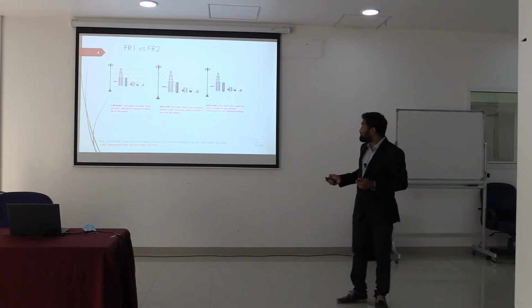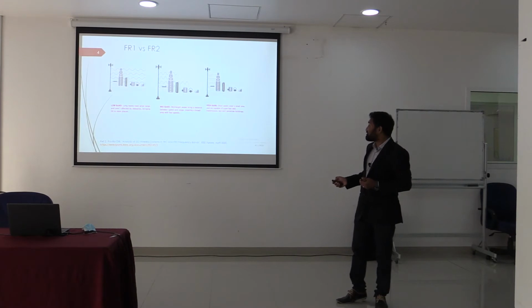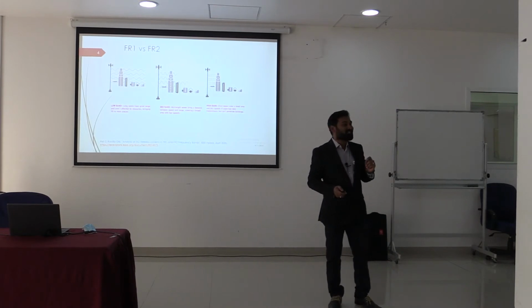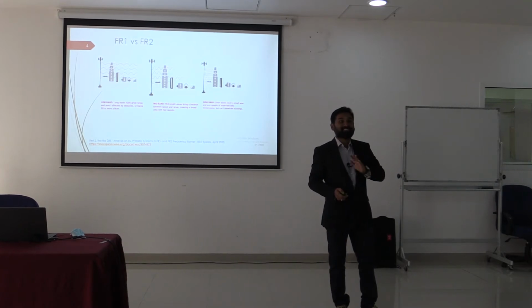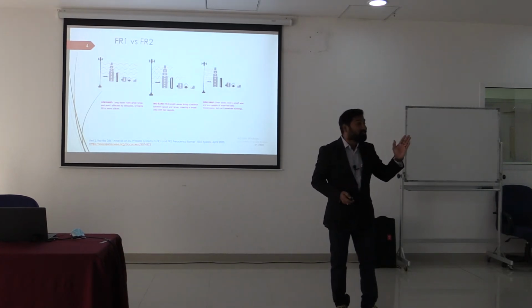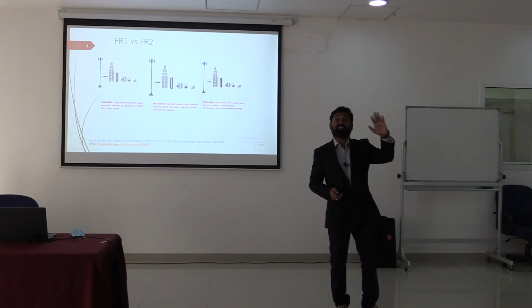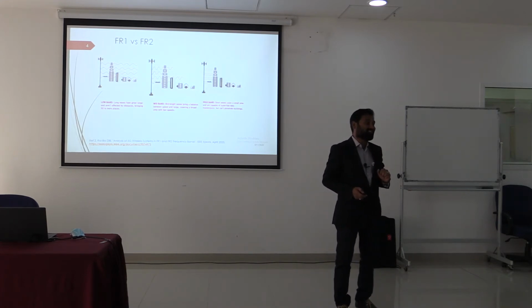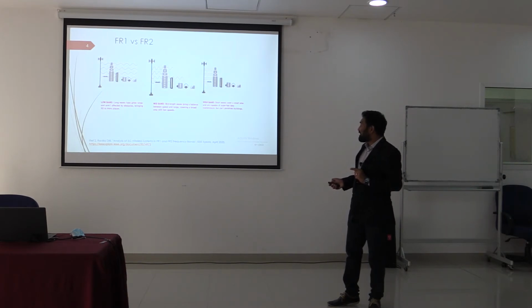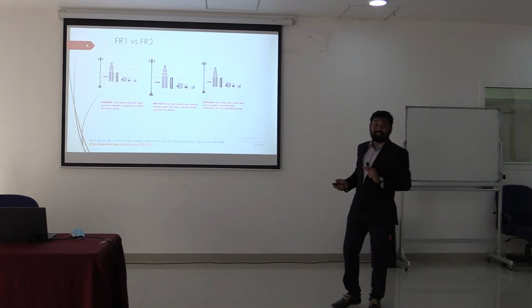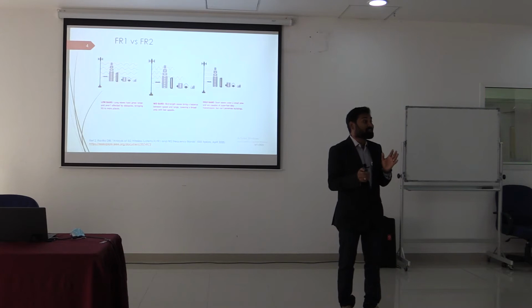The advantage of these bands is long waves. The wavelengths are very long. The advantage of having long wavelengths is that it can cover a large geographical area. The reason is that these waves easily penetrate through buildings, so they can cover a large geographical area. That is the main advantage. But the problem is, it is only a 700 megahertz spectrum. It cannot bring a higher data rate. So you can get greater coverage, but the data rate, the speed or the throughput, is very minimal.